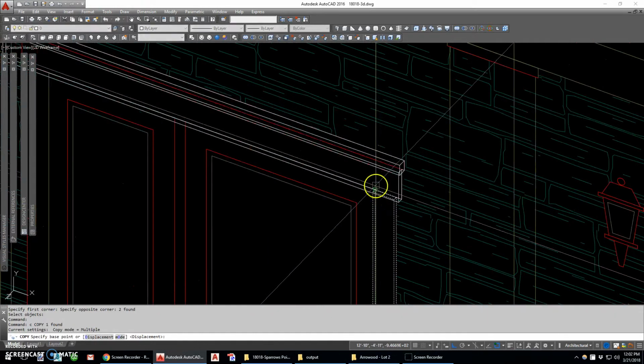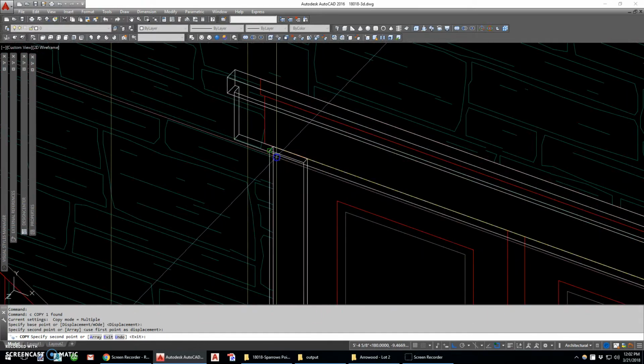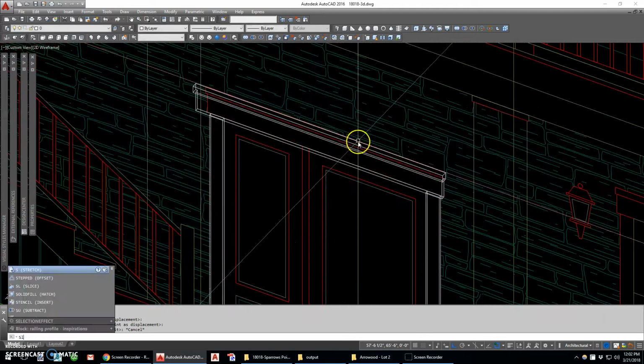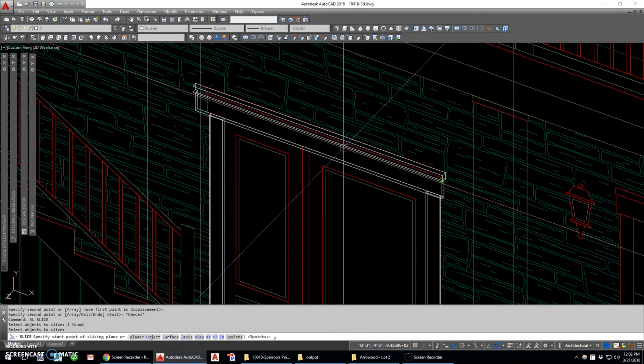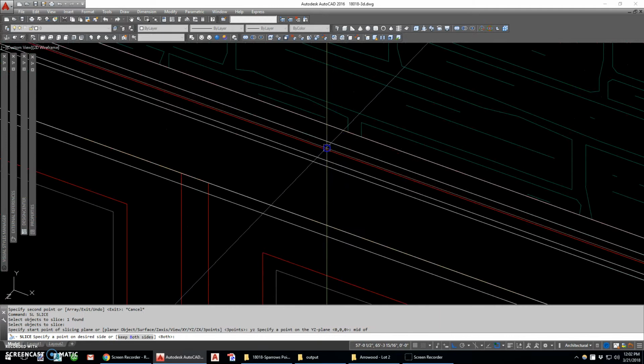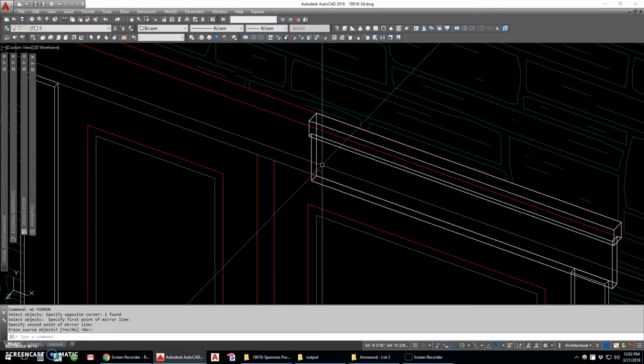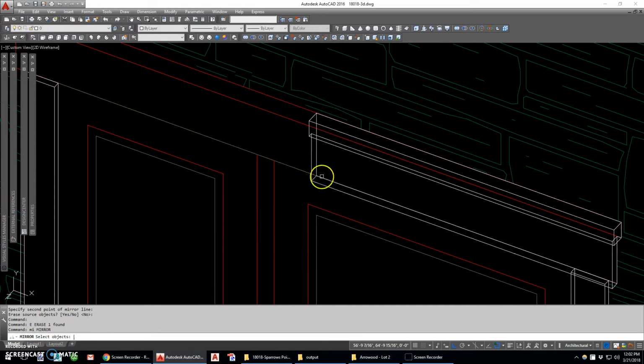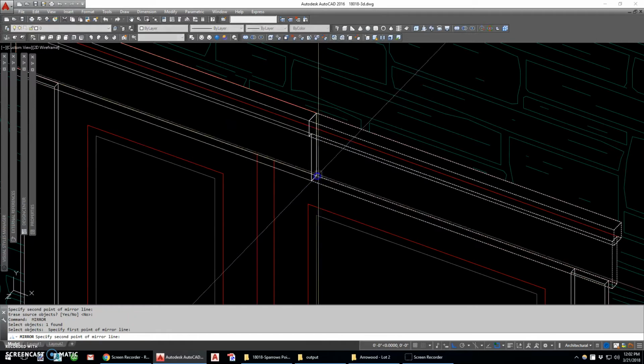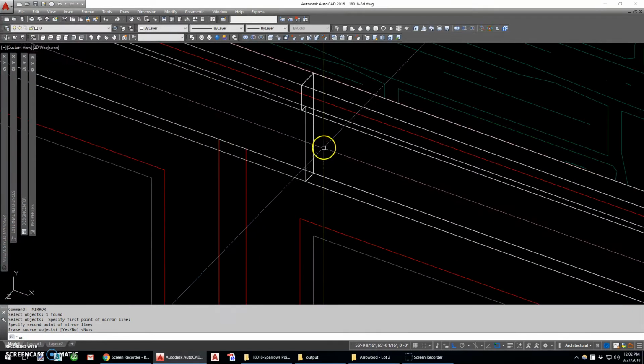And I'm going to go ahead and just copy this vertical over there. And something happened here. I want to reslice this at the middle point of that header and keep that side and try mirroring it again. Whoops, I just mirrored it over itself. Mirror. Did it again. Mirror. There we go. Now I'm going to union all that stuff together.